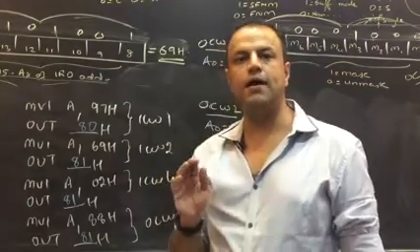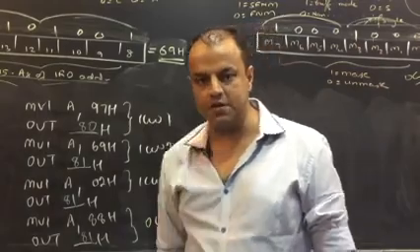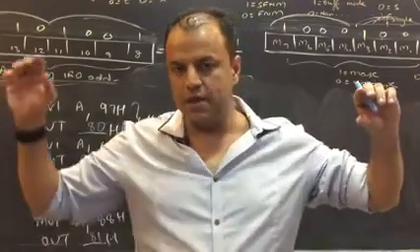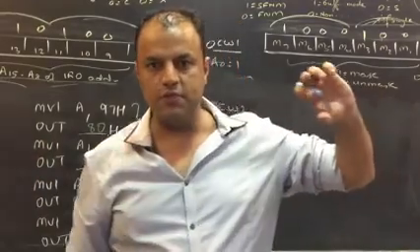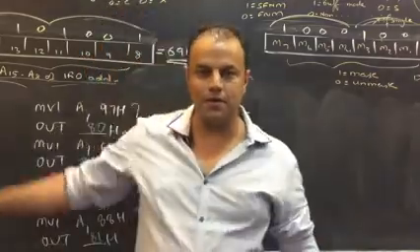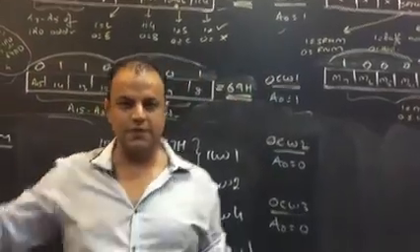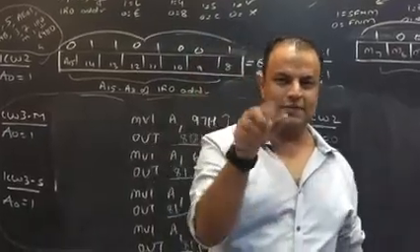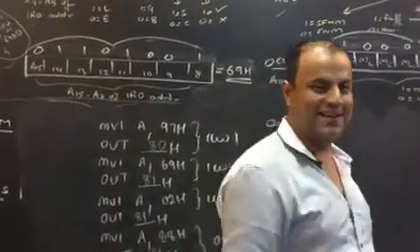80 and 81 are addresses. When the address changes, some bit of the address will change. If you look at 80, 1000 0000, that's the binary form. 81, 1000 0001. So the only thing that changed between the two addresses was the lowest bit of the address. What is the lowest bit of the address called? A0. The commands for which A0 is 0 are these three commands: ICW1, OCW2, OCW3. They have A0 as 0. They will be given at the address 80. The commands for which A0 is 1 will be given at the address 81.